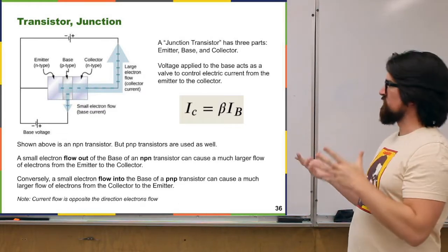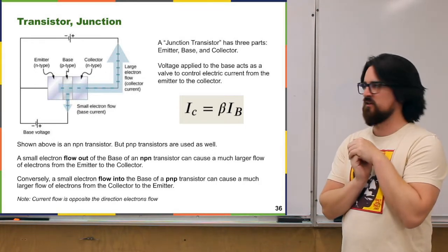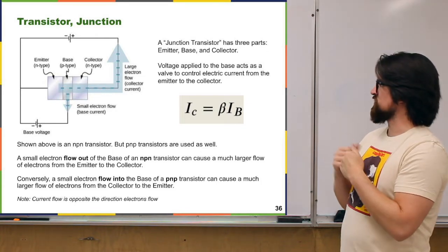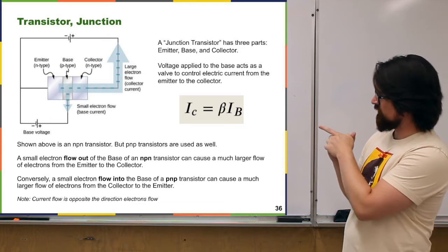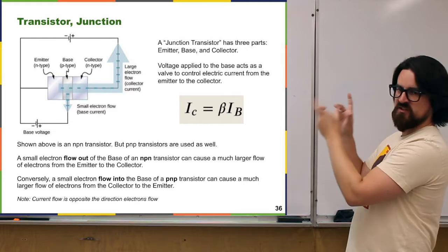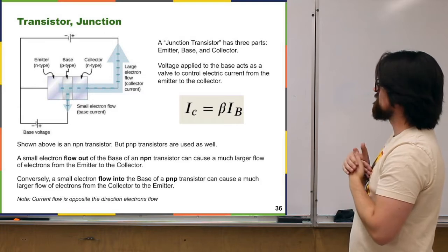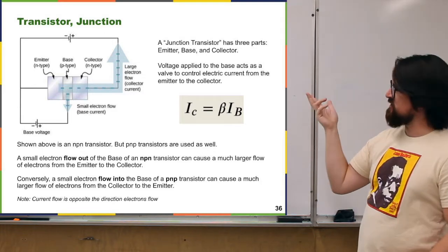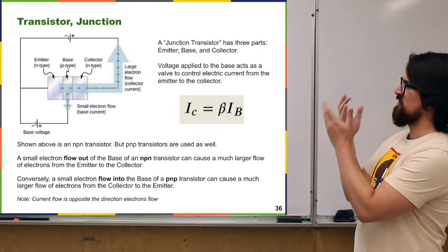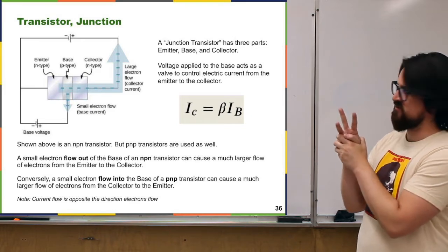The next simplest thing is to sandwich these doped semiconductors, and you end up with what we call junctions, or transistor junctions, or junction transistors, which will either be NPN. In the picture here, you have two chunks of N-type semiconductor sandwiching this P-type semiconductor. They typically have names for each of these pieces. The emitter and the collector are the outside of this sandwich, and the base is the middle. And in a transistor, you have three connections, one to each of those pieces.